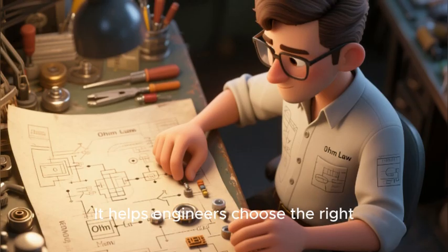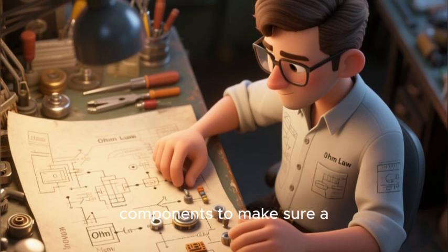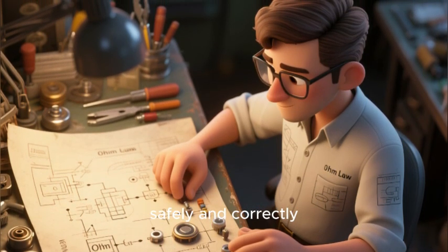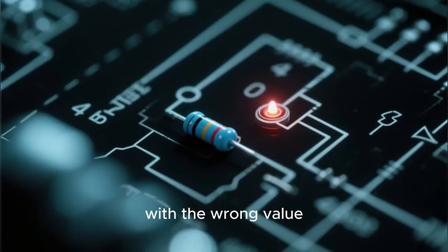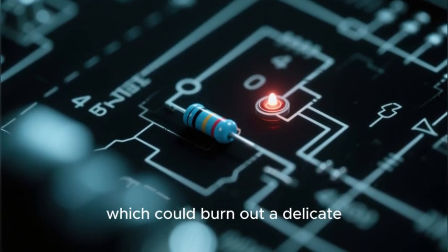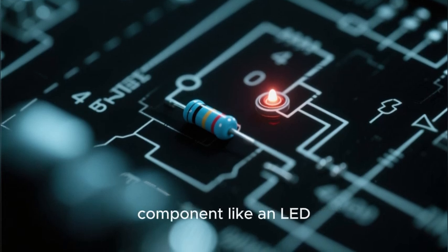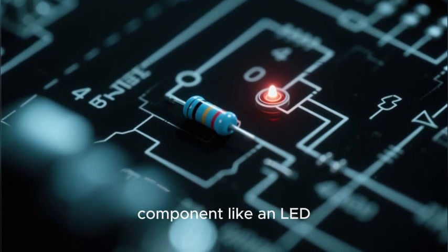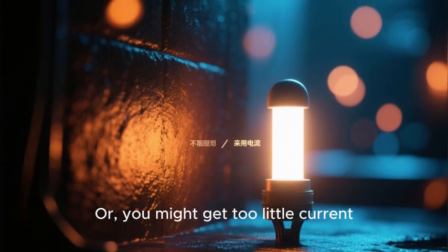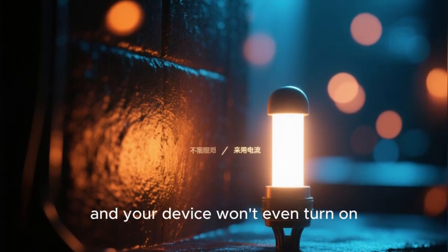Why does this matter? Well, for anyone designing or fixing electronics, Ohm's law is everything. It helps engineers choose the right components to make sure a circuit works safely and correctly. If you use a resistor with the wrong value, you might get too much current, which could burn out a delicate component like an LED. Or you might get too little current and your device won't even turn on.